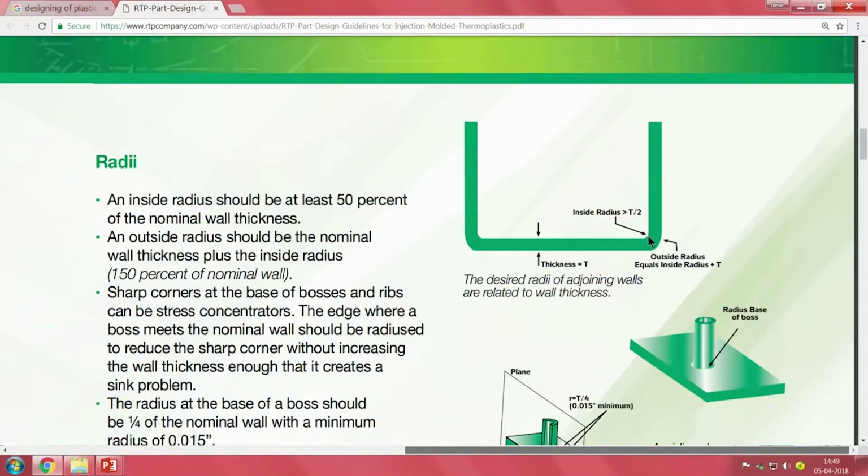Like all catalog claims, under favorable conditions, whatever they claim, saying you can get a resolution of 0.1 or 0.05 millimeters, is for test samples. In your actual sample, things will vary. So, you will get a small staggered thing with a set of steps here, which by itself is not bad, but generally it is not worth building up those things. So, what people generally do is they build straight here, and if required attach a rib here from outside, or build a rib directly inside, or leave it like that.